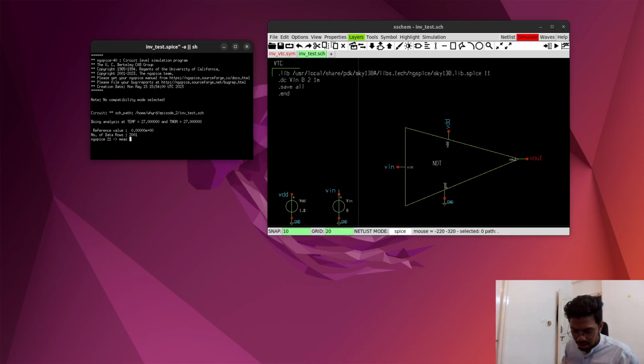So it's measured from the DC simulation, a variable whose name is VM or anything you like, when V in is equal to V out, and see it got improved. 0.86. It is better than 0.83. You'll get a much improved noise margin now, and in general we use this ratio only.